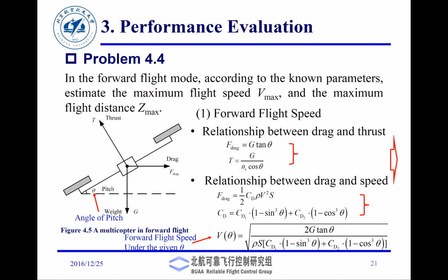For that, you use the exact same equations, but in that case, you add a certain pitch angle, because as you know, quadcopters are under actuated systems. So you have to have a certain pitch angle, but please understand, you cannot pitch quadcopters beyond a certain pitch angle because they would flip over.